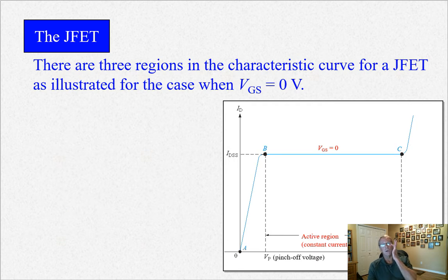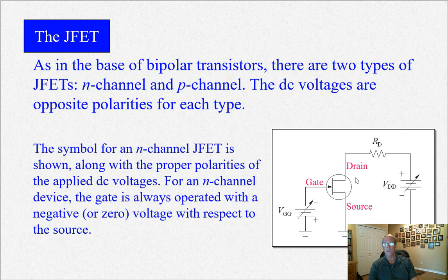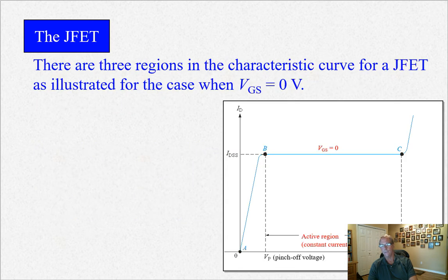So here's a transfer curve, characteristic curve, showing the VDS, drain source voltage. It's similar to the VCE of a BJT, right? If we go back here, so drain source, this would be kind of like the collector emitter. VDS this way. And then here's ID. This is the drain current. So this would be like your IC for a BJT. Very similar.